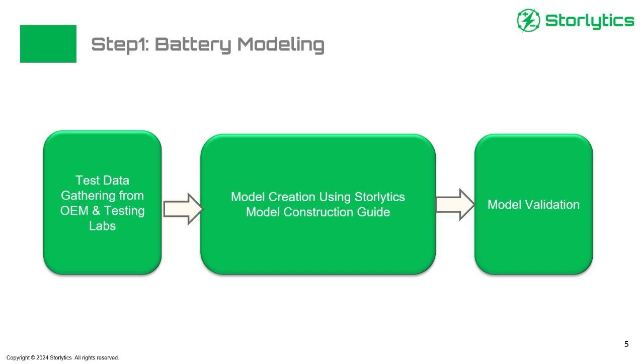But getting data, either from the OEM or testing labs, creating models using that data, very accurate models that capture all the details, voltage, internal resistance, self-discharge, efficiency, degradation, and then validating that model.